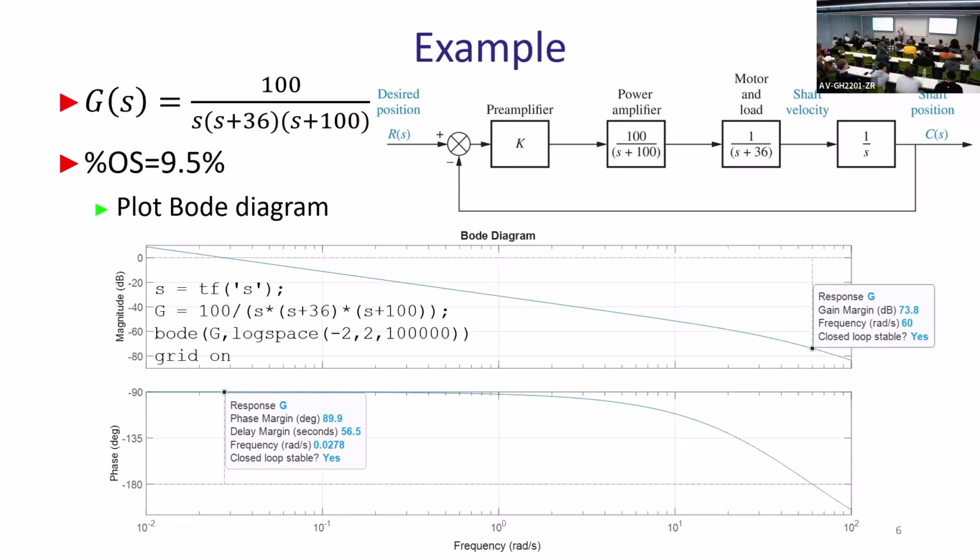So omega squared will give you the free coefficient in your second order approximation, and twice zeta omega will give you the second coefficient in the polynomial of poles, right? So this way you estimate the system based on the step response, for example. But you have other ways to estimate systems. You have optimization, you have all kinds of tools to estimate systems.